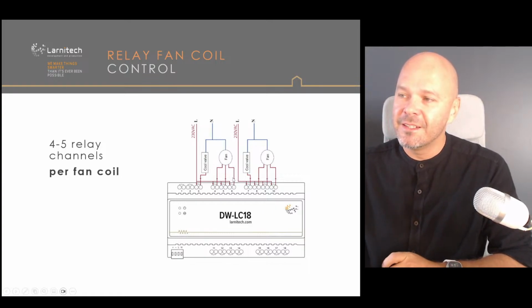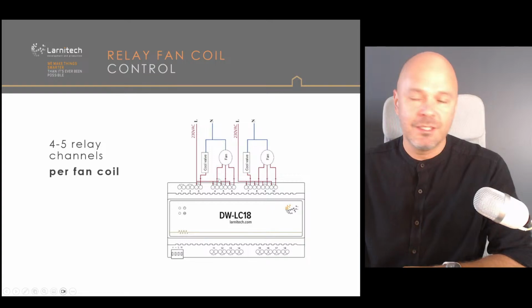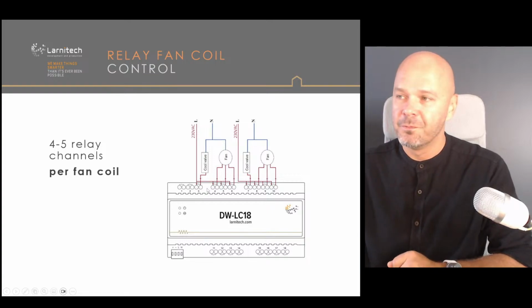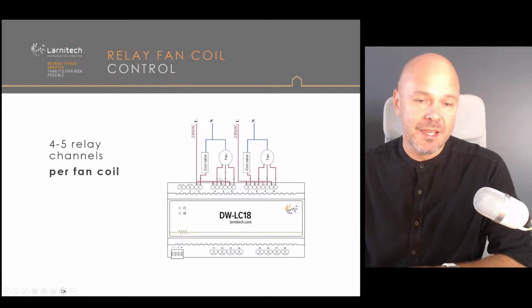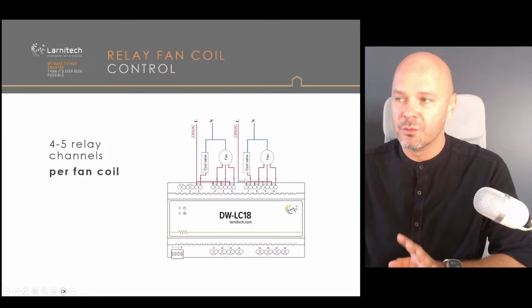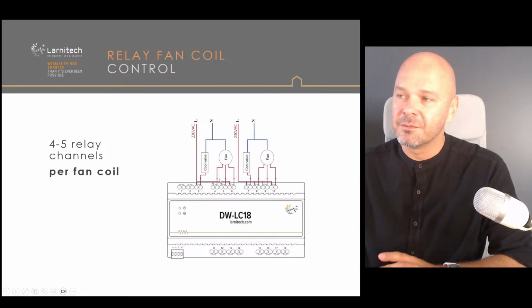Here you can see that to any Larnitech relay you can connect the fan coil, and this will be almost the same as the connection to a typical thermostat. You can connect 24 volts, you can connect 20 to 30 volts here. So this will be the same connection, cool valve and then fan. Also can be heat valve.